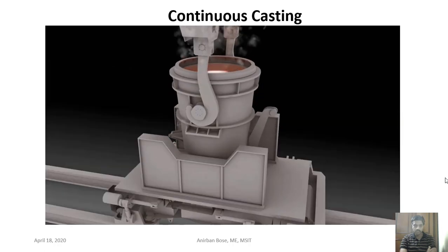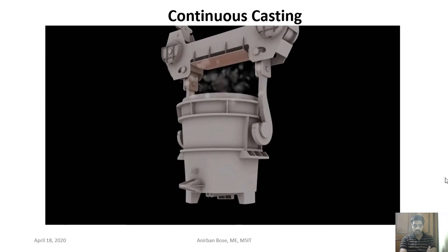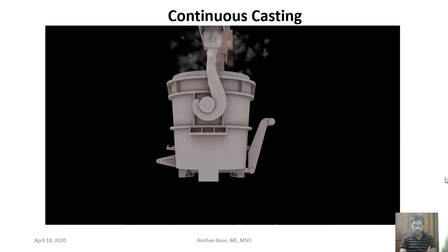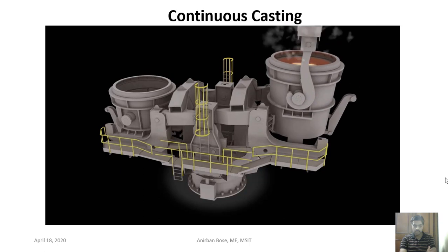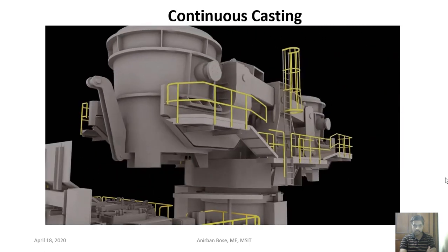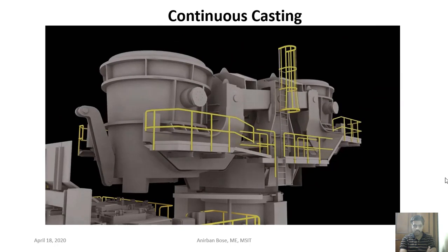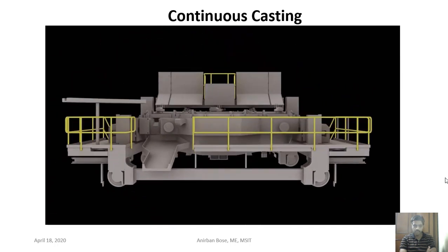Once it reaches the caster, a 300-ton crane picks up the ladle. This crane lifts the ladle about 100 feet before placing it on a large rotating turret. Once the ladle is ready to cast, the turret rotates the ladle over top of the tundish. When the ladle reaches over the top of the tundish, a refractory valve opens to allow steel flow from the